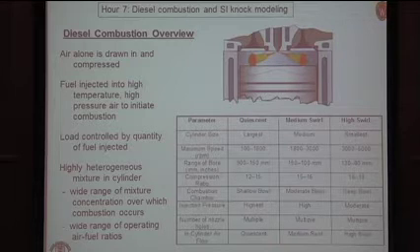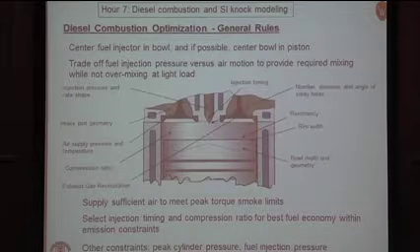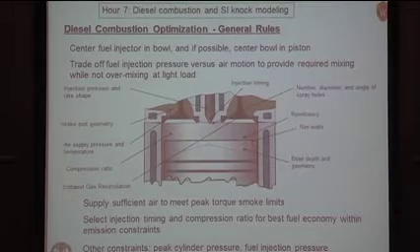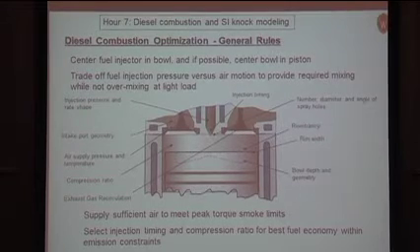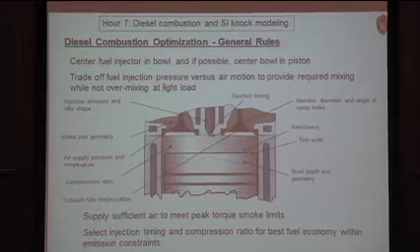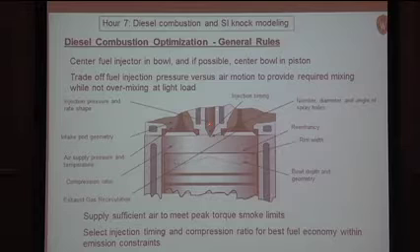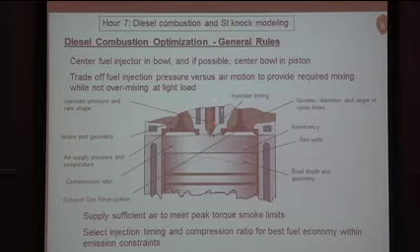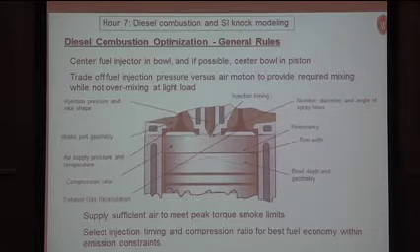So some of the other parameters you can see here in this table characterize these different sizes of diesel. There are some guidelines, if you were to design a diesel engine, that you have to respect. And these have been learned over the years. You know, diesel is over 100 years old, right? Rudolf Diesel started designing his engines in the 1890s. What people have learned is it's a good idea to center the fuel injector in the combustion chamber, and preferably to have it centered within the piston bowl, because if you're doing the injection near top dead center, you want to have as symmetric a flow field as possible to prevent issues that would come from non-uniformity of the pressure release.